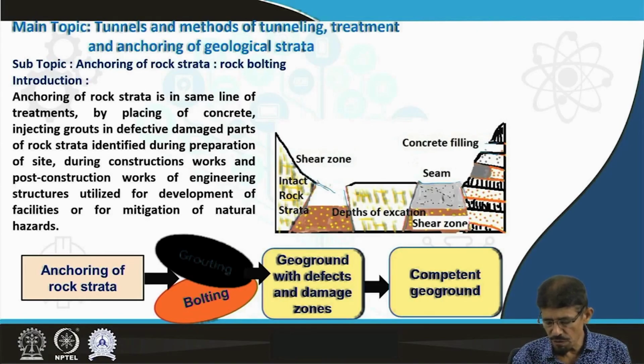We are going to first excavate the weak zones, then fill with concrete or inject some grout to enhance the strength of rock strata through seam treatment.